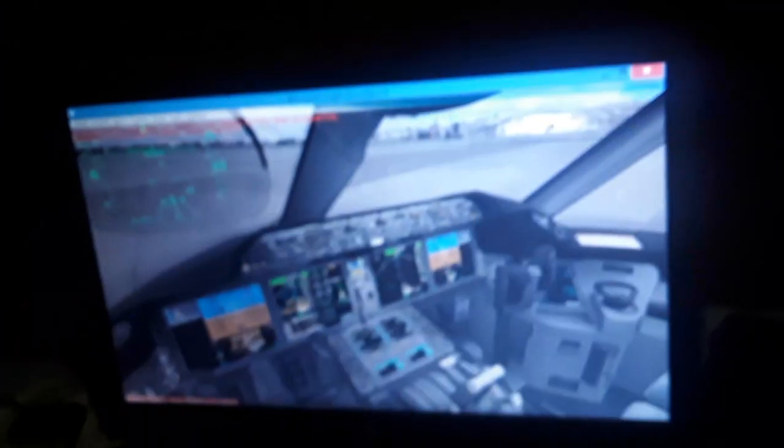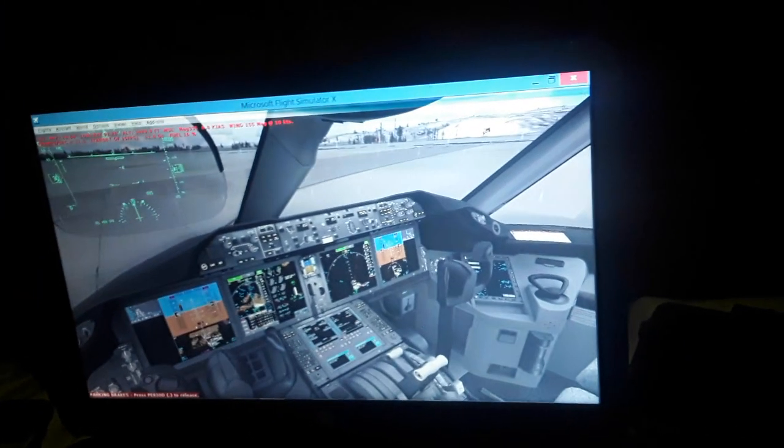The altitude selected from the autopilot and flight director system panel, and the vertical rate of climb and descent of the aircraft in tens, hundreds, and thousands of feet per minute. That also determines the trigonometric angles in degrees the aircraft can climb or descend, the steepness of the angles it can climb and descend. So we're gonna have all the information displayed in the primary flight display.